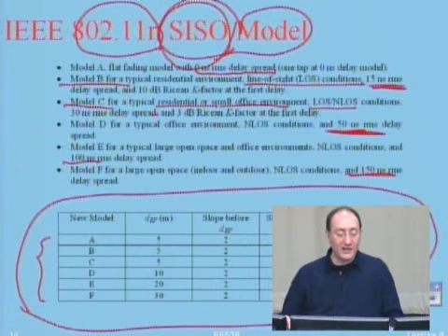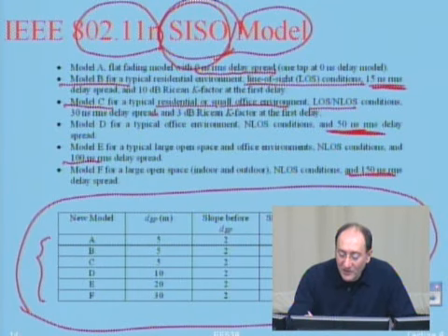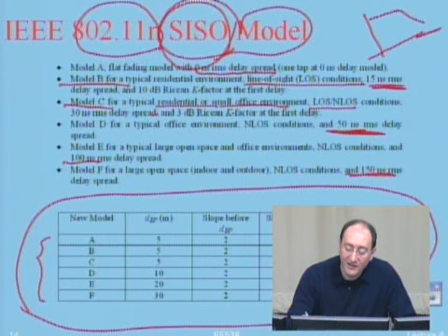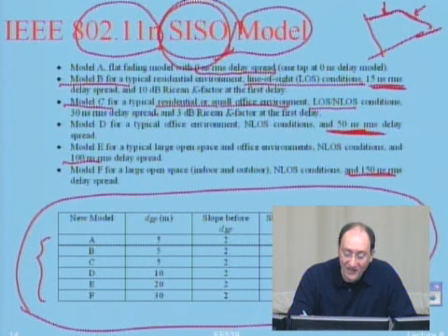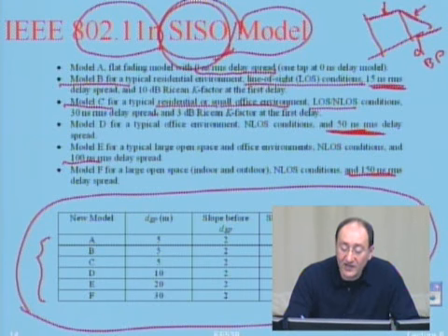How do they define the path loss model? The path loss model that they select is like this. If you remember, I have two slopes. Do you remember? We used to call them partition models. There is one slope which comes up to a distance break point, and there is another slope in here.